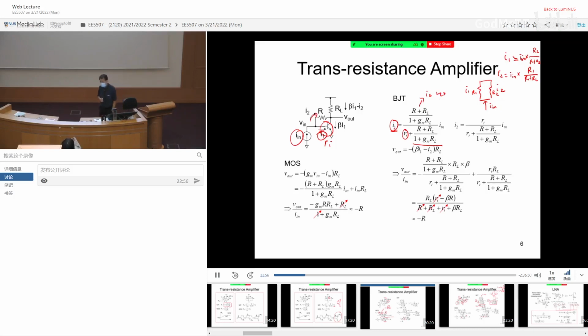This is how I obtain I1. And then to obtain I2, again, this is the total resistor, but I replace the numerator with the I1 branch resistor. Okay? And then the VR, same thing: total current beta I1, subtract away I2, and then multiply by RL, you add the negative sign. And I1, I2 are already derived, so I just have to substitute.